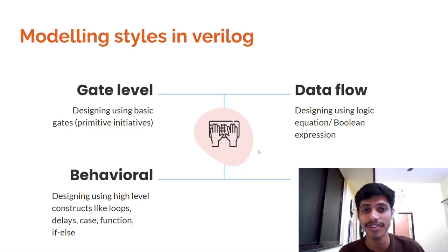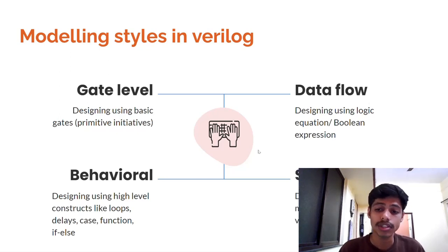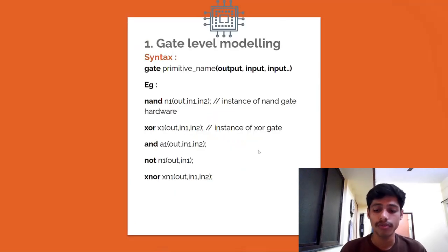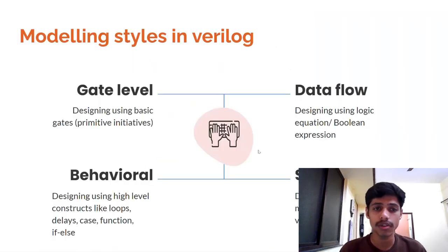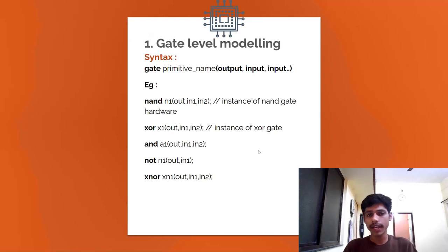There is nothing changed in Verilog and VHDL. They both are very much similar. Structural modeling: in structural modeling, we use instances, smaller parts, which are used in data flow modeling or behavioral modeling. So we are not going much deeper into behavioral or structural modeling, and we will implement the circuit by using data flow modeling only.